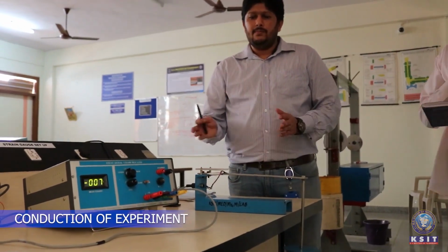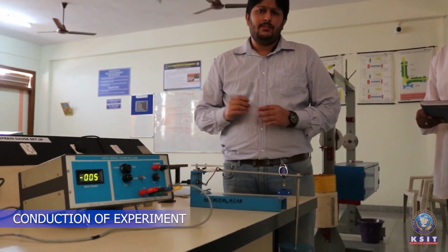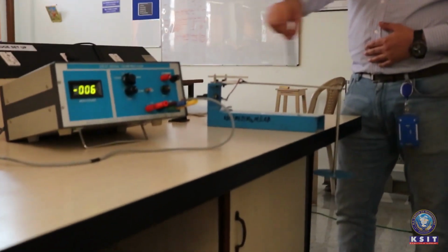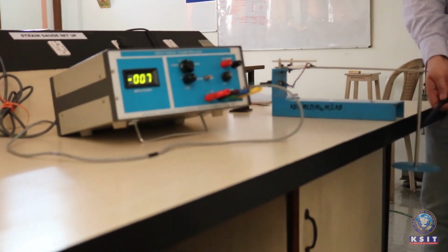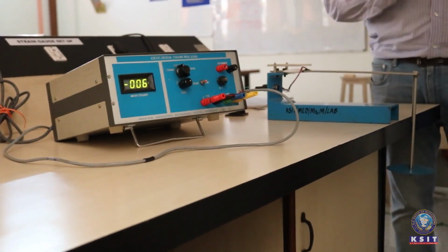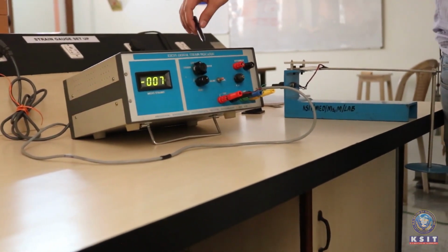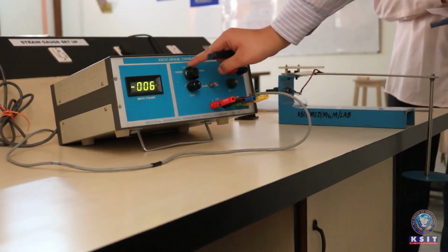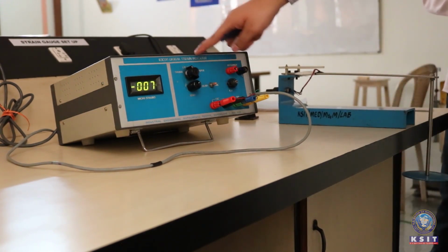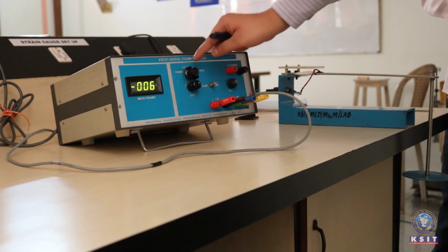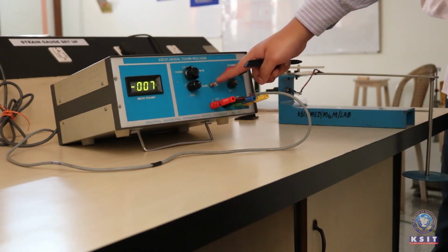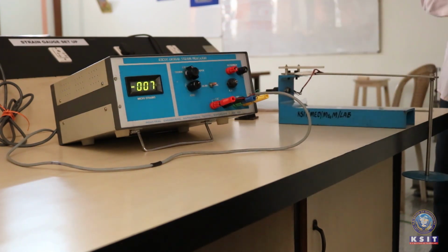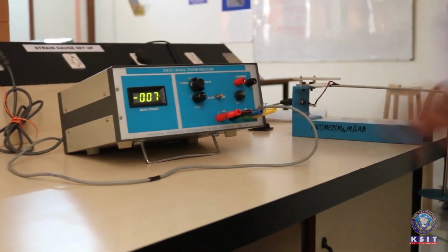Okay, so now what you're looking at is the experimental setup of the strain gauge. As I explained in the diagram, we have the beam. This is the cantilever beam, and there's a provision given for weights to be added. We have to calculate the bending stress. One thing that you have to note on this instrument is there's a decal which is called strain. The knob should always be pointed towards strain, not towards EXE volt or MV output. It has to be always pointed towards strain, and this knob should be pointing towards read. These are two things that you have to keep in mind. And this is the reading where we get, and this is in micro strains.